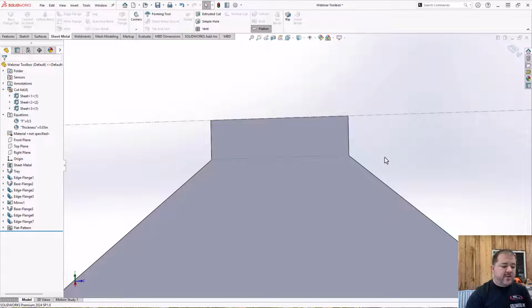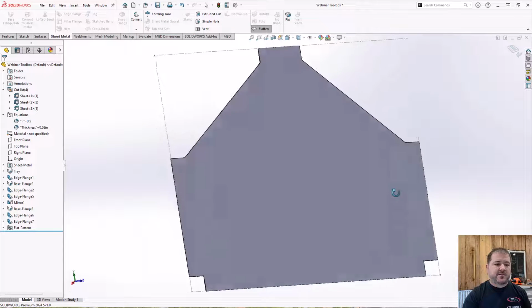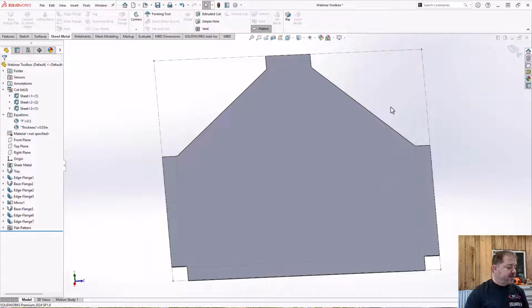And the way we calculate that in SOLIDWORKS is usually with something called a K-factor. Now, you may have heard bend allowance, bend deduction, setback, things like that. Those are really great for back-of-the-envelope calculations. If you're trying to build a section of C-channel and you want to know how big to create your raw piece, those bend allowance calculations make it easy to just say, boom, boom, boom, add them all up, call it good, that's the size I need.